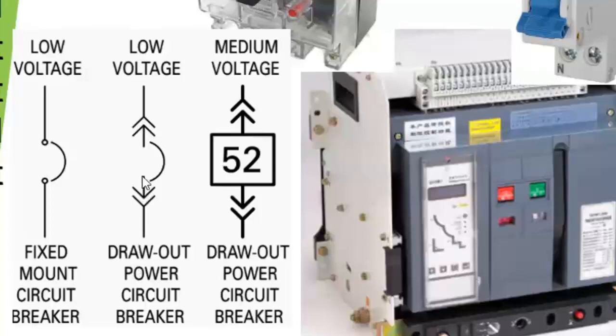So when you see this symbol, that tells you that the circuit breaker in that particular circuitry could be racked out. Apart from these two, the device numbering can also be used to represent circuit breakers in electrical diagrams. The device number for circuit breakers is 52. So when you see 52 in a box like this in your electrical diagram, that tells you that what you are looking at is the circuit breaker. And of course, the double arrow up and down tells us that this is also a detachable circuit breaker that you could rack out of the circuit or the cabinet.